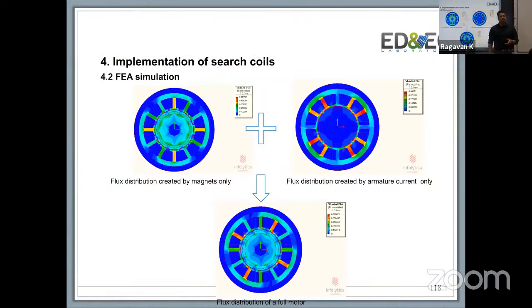So the question really is, what does this surge coil need to be? It has to be an unenergized coil, still made out of copper, with the same material properties as before. So you are invasive in how you are approaching it, adding an extra coil. But the basic principle still follows Faraday's law. The number of turns you need is a function of how much current you're applying, because that will cause the field, and N dφ/dt will dictate how much N you need in order to be visible. I believe in our case we had 3 turns on our motor.